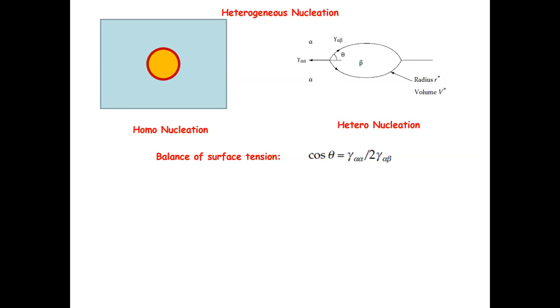So what we do is we consider a particular shape for this nucleus. Sometimes we call this an embryo. This shape is very similar to the shape that we already analyzed in our homework for heterogeneous nucleation at the solid-liquid interface, at the wall. We approximate the nucleus as a spherical cap. So basically what you see of this embryo, again, I'm trying my best to draw, is that we just have two of those caps.